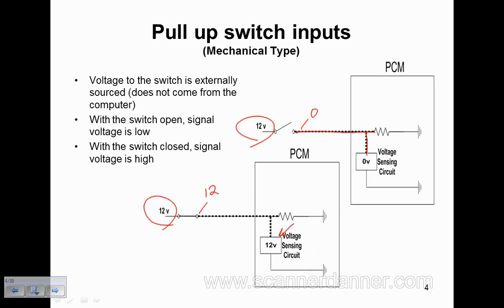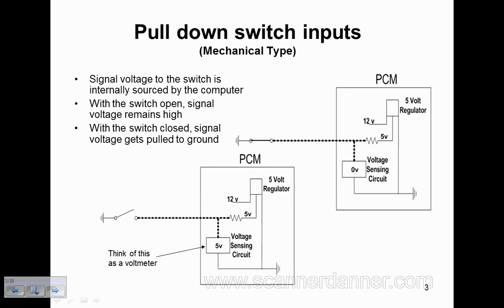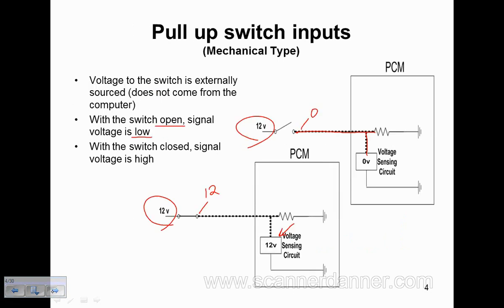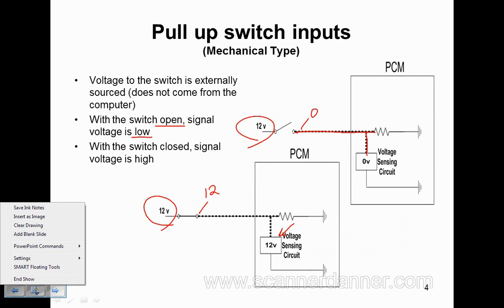Pull up design. So it's opposite. Look, switch open, signal voltage is low. Let's back up a page. Switch open, signal voltage is high. So you can see that they're opposite of each other in operation.